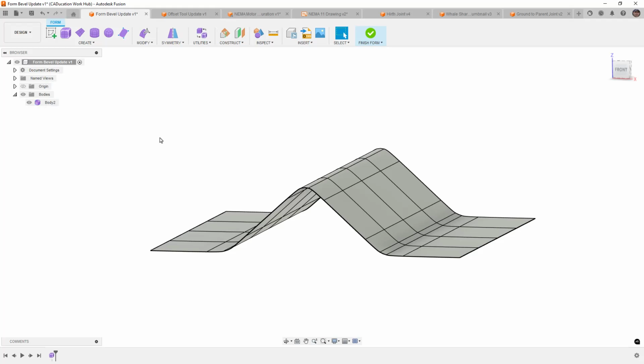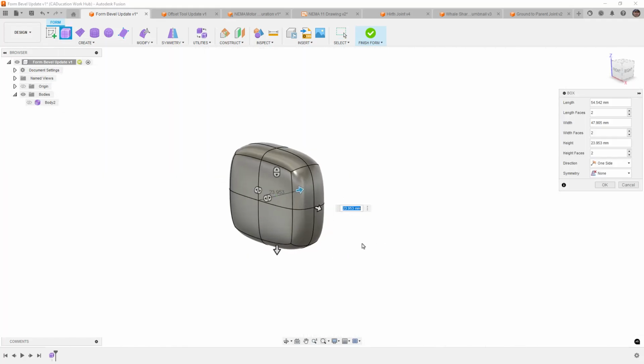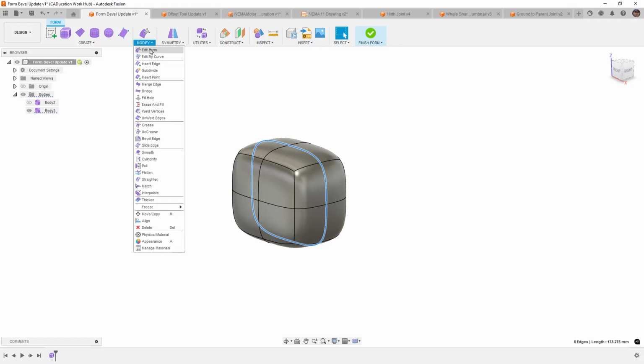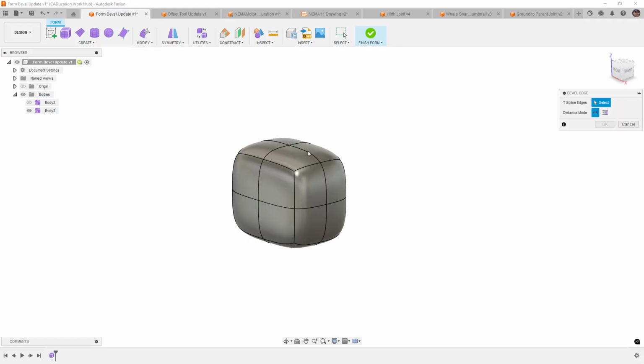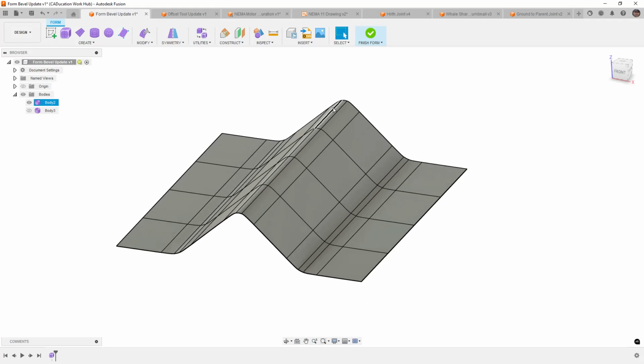I have found some limitations to this. I'm not 100% certain, but in the past, I feel like the bevel tool could work on any selected edges. So I would use it to insert edges in certain places. However, now when we use the bevel tool, it's not going to be available if we have an internal edge like this. It has to have a higher transition angle. And I don't know if that's a new thing, a change, or if it was like that before and I just never noticed. But I feel like we were able to use bevel on pretty much any edge in the past. So keep in mind, or just kind of keep an eye out for that. If you notice that as well, leave a comment and let me know. Hopefully, if it's just a bug, then that'll get fixed or changed.